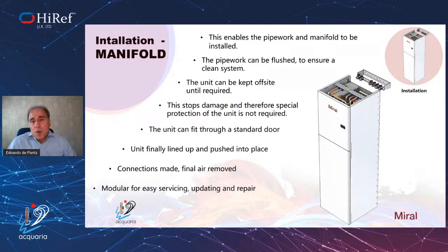Then only when the apartment is ready and finished, I can bring my heat pump on site, easily fit through the door, and line up the connected piping, flush the system and take the air out, and the unit is ready to be operative. So very quick and easy to install, for peace of mind of the construction company, but also of the installer.